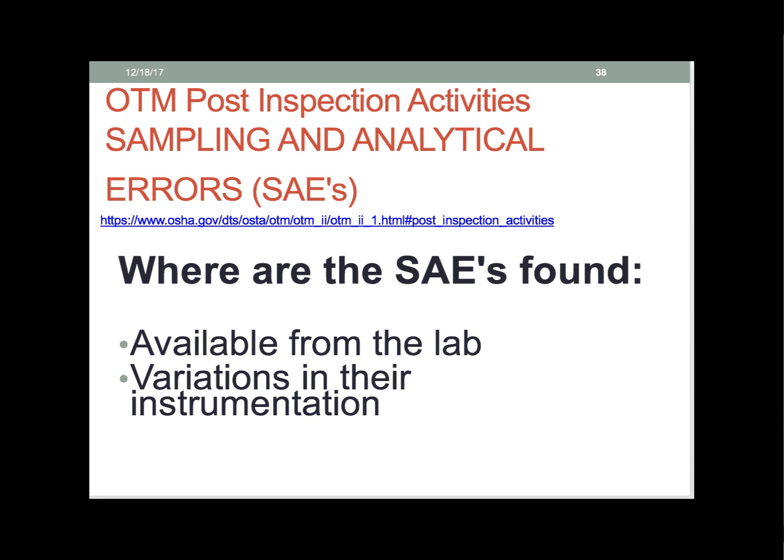And we'll look at our standard analytical errors a little bit later. But first I'm going to do two more example problems for you. And this serves as our introduction to calibrating sampling pumps, and different types of errors that we're going to try to guard against when we're sampling.